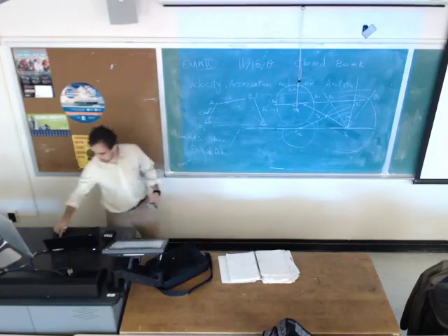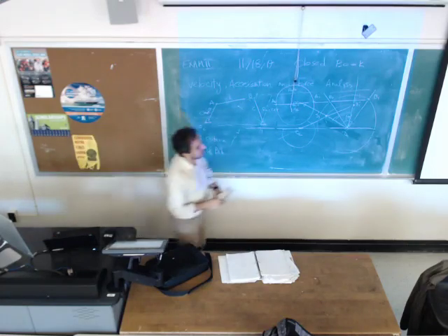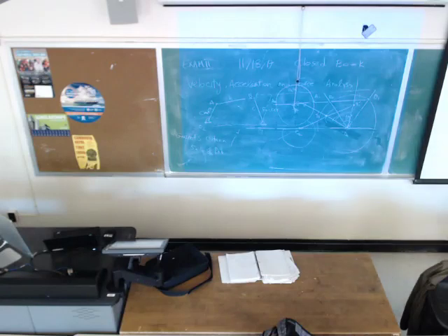Question on this. This slide is showing the steps. You pick a point, O4, any point, and draw this line at any desired angle with the ground line. Pick a point on this line, draw a circle or part of the circle with this center and this radius, such that it gives us the intersection of the circle with the other line.